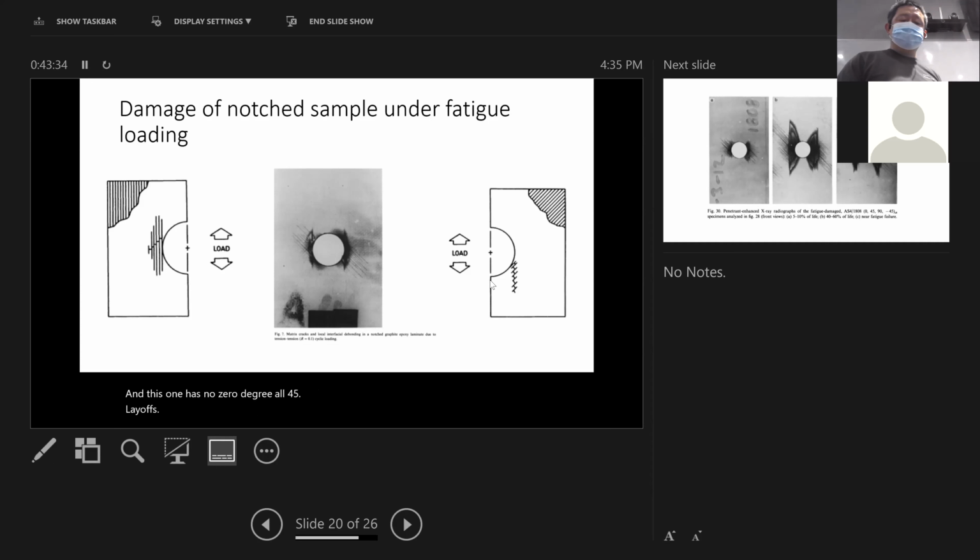This is the type of material where you would see the wear in and wear out phenomenon, as I showed before. The material initially becomes stronger, and later on becomes weaker. And the reason it becomes stronger is because all the cracking events occurring near the edge of the hole reduce the effective stress concentration.